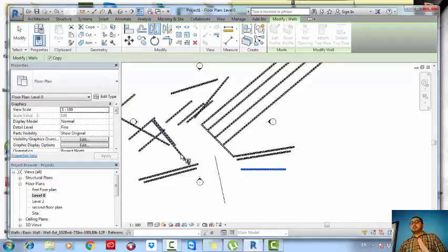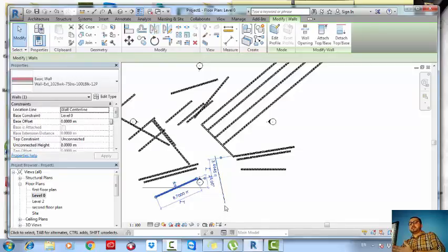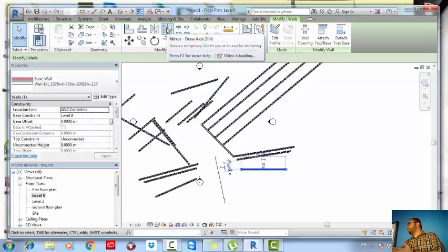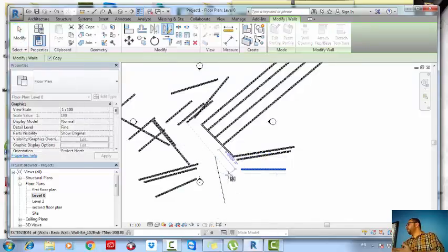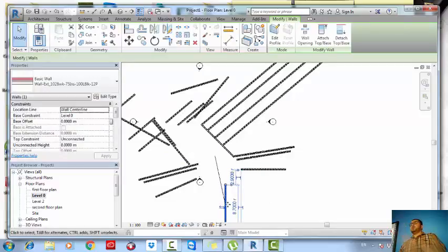It's an object in the viewport, and I can use it as an axis for the mirror. If I select this one, mirror, then I can select this axis. If I select this one and I click on mirror, draw an axis, I should draw an axis just like in AutoCAD. From this point to this point, it will be mirrored. Fine.